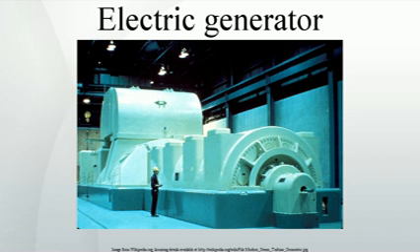The dynamo was the first electrical generator capable of delivering power for industry. The dynamo uses electromagnetic induction to convert mechanical rotation into direct current through the use of a commutator. The first dynamo was built by Hippolyte Pixii in 1832. A dynamo machine consists of a stationary structure, which provides a constant magnetic field, and a set of rotating windings which turn within that field. On small machines the constant magnetic field may be provided by one or more permanent magnets. Larger machines have the constant magnetic field provided by one or more electromagnets, which are usually called field coils.